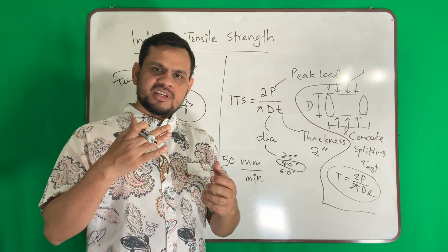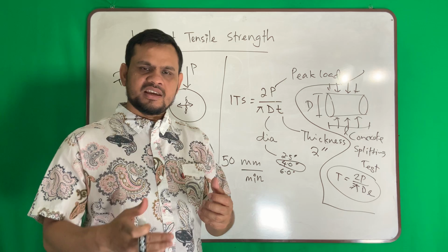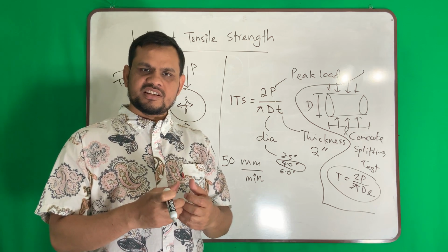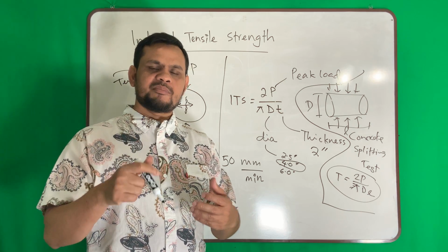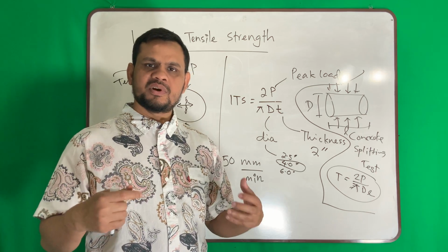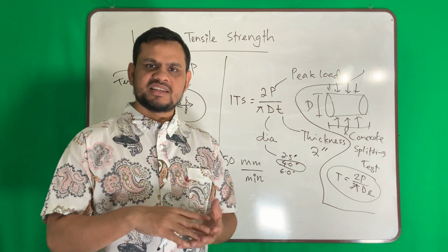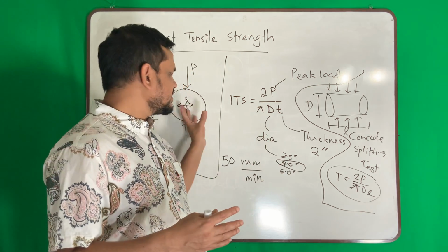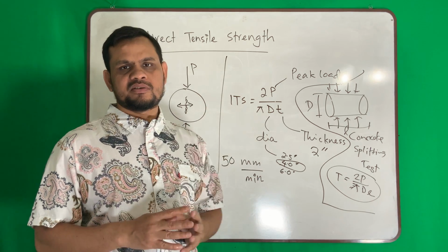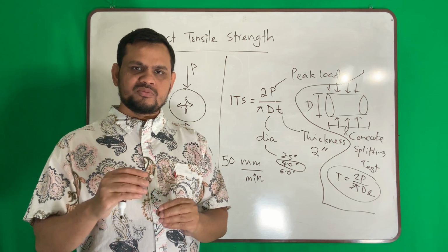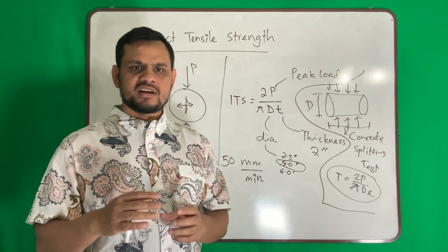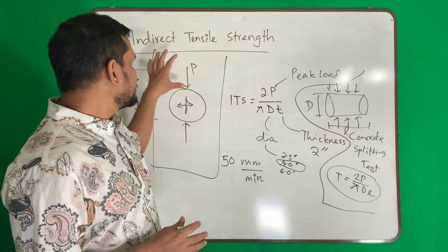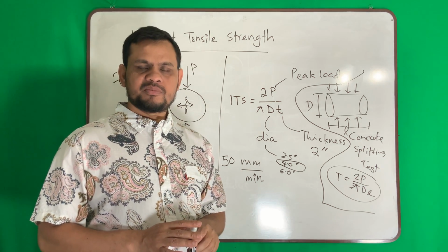If the temperature keeps on decreasing, the developed tensile stress will keep on increasing. After some time there will be a crack when the developed stress exceeds the tensile strength of the asphalt concrete. So to simulate that, or to understand that, or to measure that, we need these material properties.